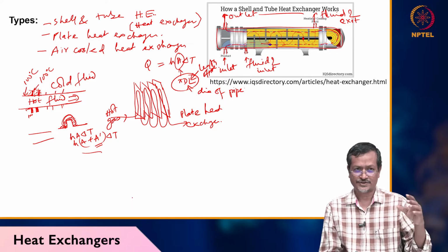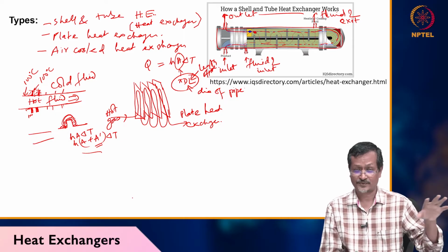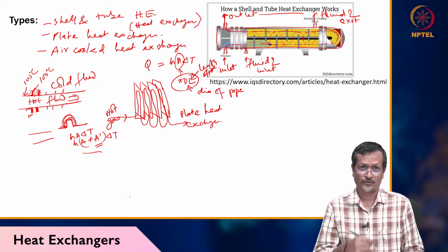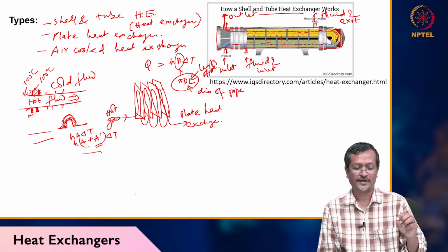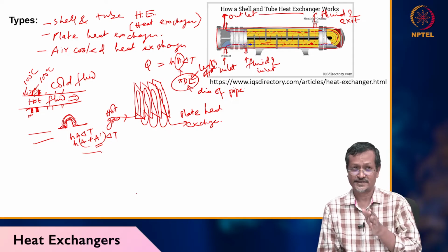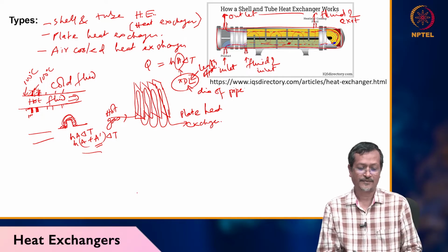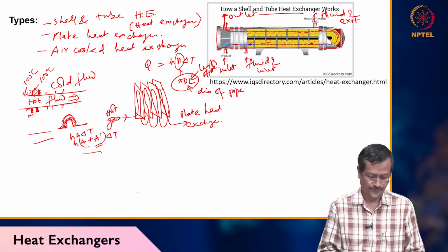Okay. In many cases this extended surface or finned surface will be used, for example, motorcycle engine cooling or cycle compressor cooling in your hostels, there will be a heat exchanger system, there will be a heat exchanger in your motorbikes or shipping machineries, there will be lots of applications, even in computers there will be a heat sink or this protrusion surface or micro channel they say. So they also have this finned or extended surface to increase the heat transfer rate.